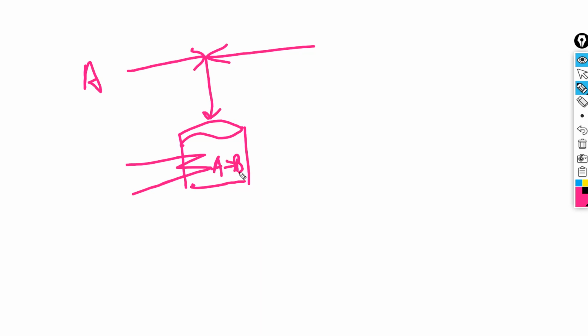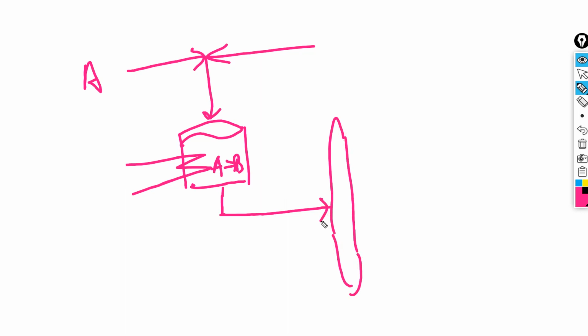Conversion is 30, 40, 50% single pass conversion, and so the reactor effluent has product B as well as a significant amount of unreacted A. The reactor effluent is distilled in a column, and you take out unreacted A up the top, which is recycled back, and product B down the bottoms. So this is our process.